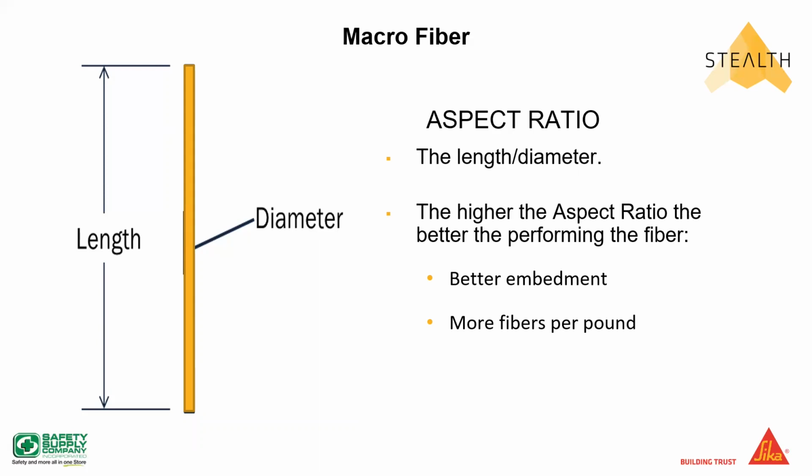Only weighs 150 grams. We have fibers with deniers that are under 20. So just think about that: 9,000 meters of a fiber that weighs 20 grams or less. That's a very, very fine fiber. So the lower the denier, the finer the fiber. Not sure if you've ever heard that term before. A lot of people have not, but I like to introduce that to you anyway. I think it's really neat to say that 9,000 meters of a fiber only weighs 150 grams. That's just not a lot of weight for a 9,000 meter length.